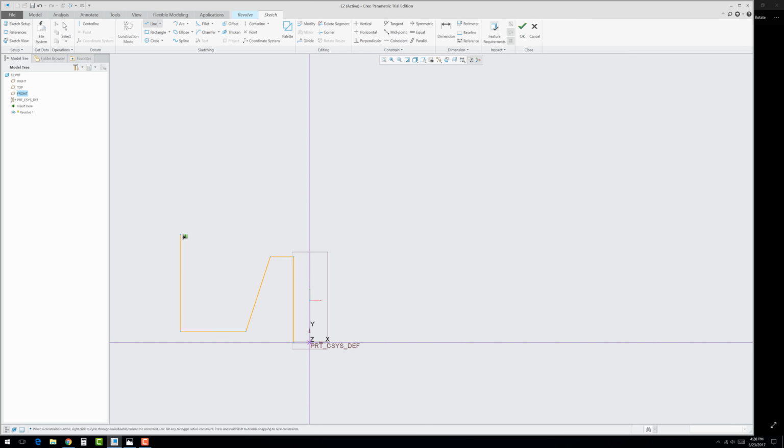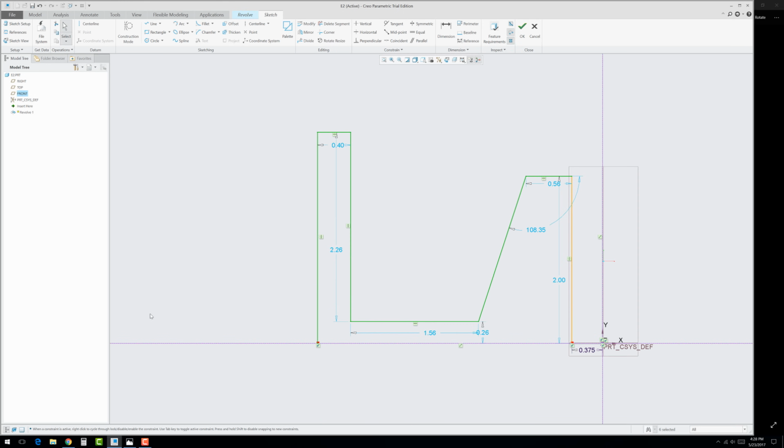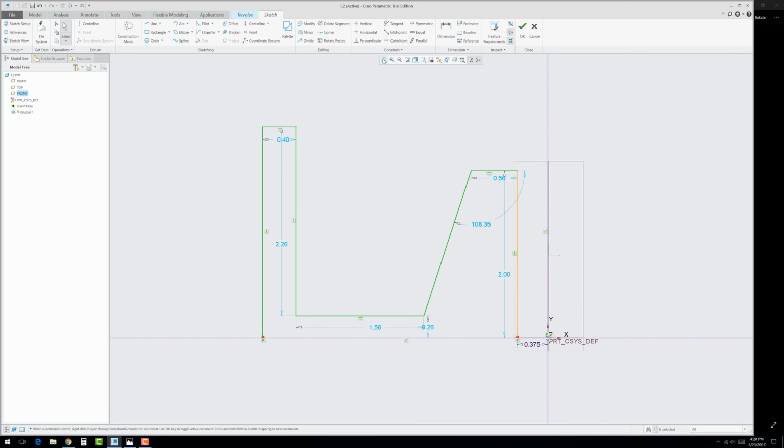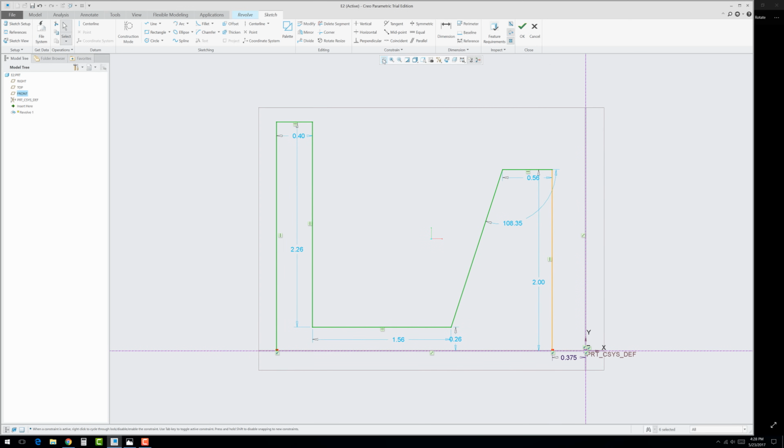Okay, drag up a line. Make sure there's no equal symbols. It's vertical. Click across here, a very short line. Click, drag down, and connect to the center line. Now to end the chain, just simply middle click, and middle click a second time. And now you could scroll in on that. Or you could go up here to zoom to fit, or refit, I should say.